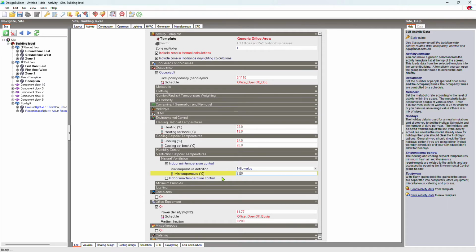You can also use detailed schedules and/or Design Builder scripting tools to enable more advanced temperature controls for the activation of natural ventilation. Scheduled natural ventilation is primarily for simple and early stage modelling, so these may be more useful with calculated natural ventilation. In this tutorial, I will use a natural ventilation set point 2 degrees Celsius higher than the heating set point. This should provide a significant deadband to prevent simultaneous heating and venting.